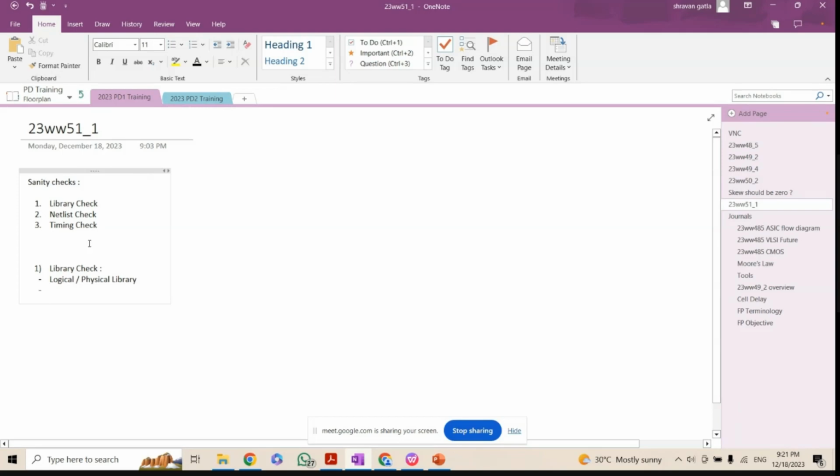Okay, like this. So yeah, I don't think you will go till this stage. Mostly, you will fix the paths at either routing or refloor planning. Mostly in these two stages only, you will fix the timings. So yeah, if it is all good, then you tape in or tape out the partition, and you are done.